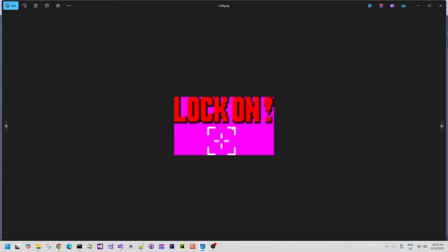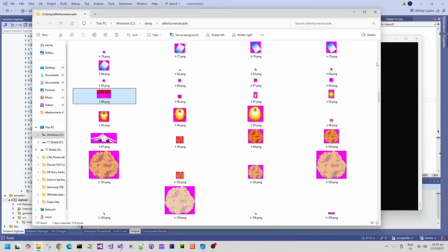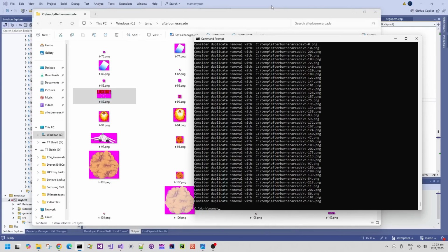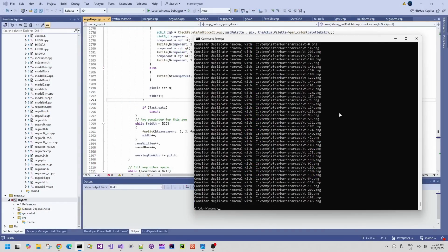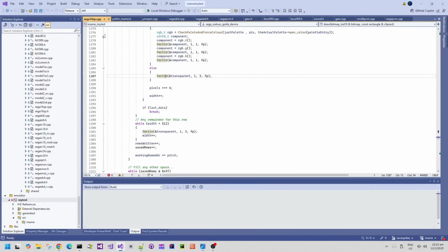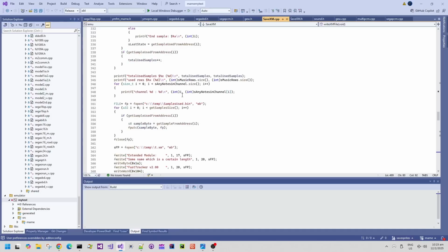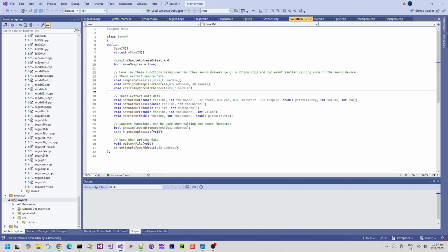The hardware doesn't actually use a Mode 7 layer for the horizon. Anyway, once I have those sprites, I can incorporate them into the demo code for the Afterburner demo using my MegaWang 2000 Turbo Edition hardware. I also added some debug code to this hacked version of MAME to save out PCM music data as an XM music file format.